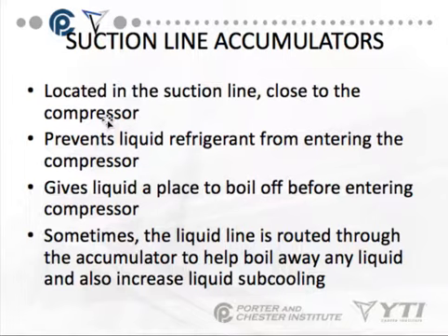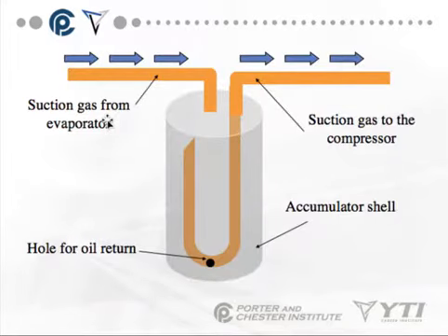When you're dealing with heat pumps in air conditioning and heating, we want to make sure we never have liquid refrigerant coming back to the compressor. So all this does is give a little bit of extra protection to the suction line and to the superheat process.